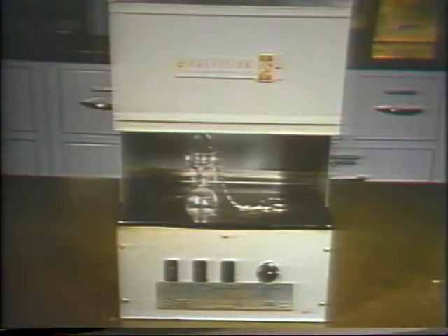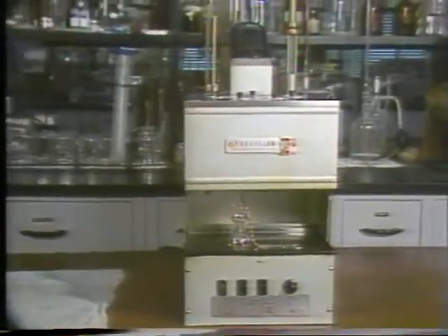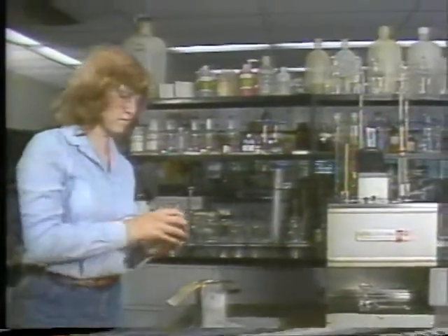A special instrument called a Saybolt viscometer can be used to measure viscosity. Even though you might never use one, we'll show you how it works so you'll have a better idea of what viscosity means. A typical Saybolt viscometer has an upper section with several chambers housed in an oil bath. The oil bath maintains the fluid in the chambers at a constant temperature. The lower section contains a flask for collecting the oil drained from an upper chamber.